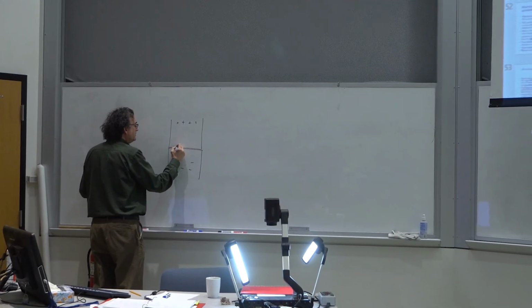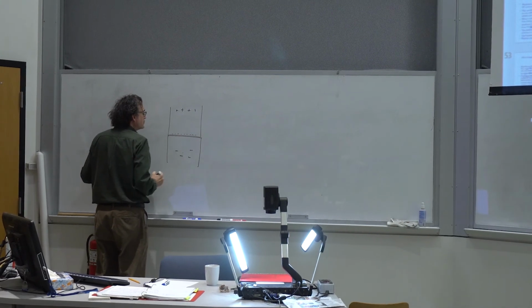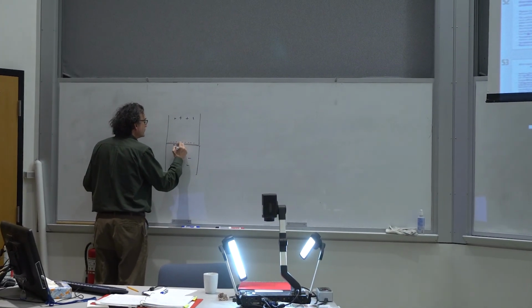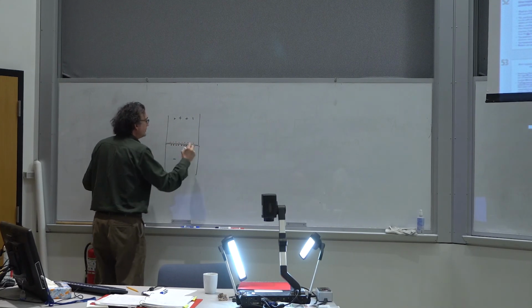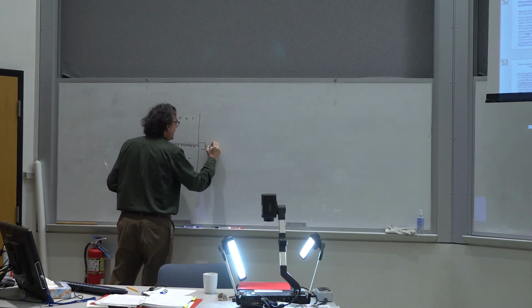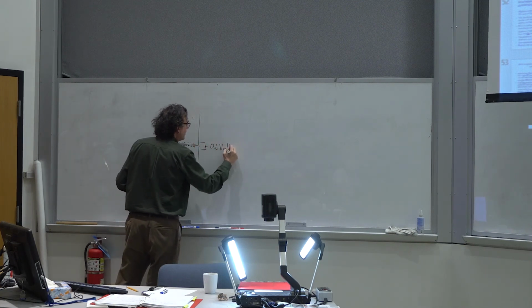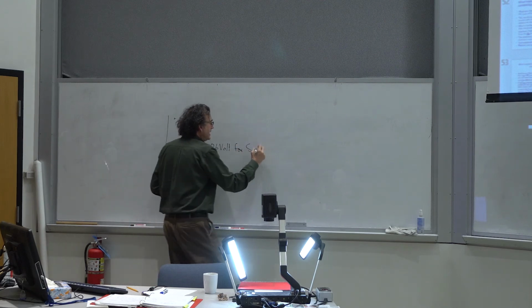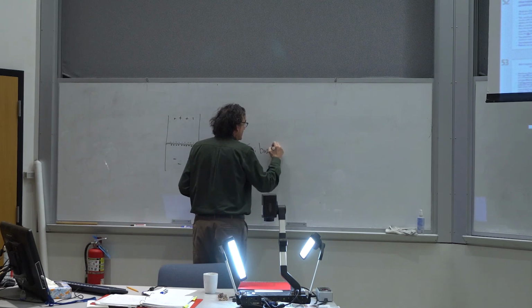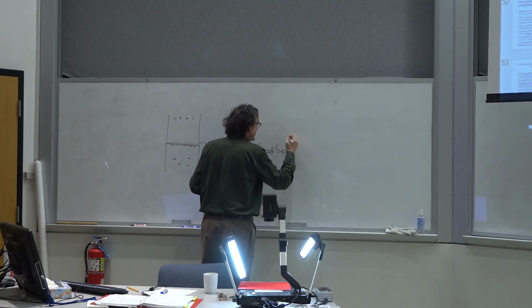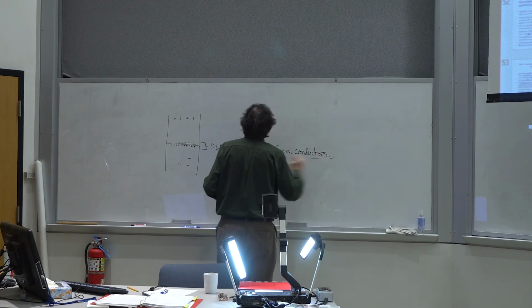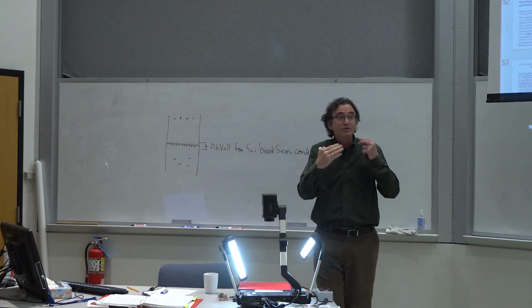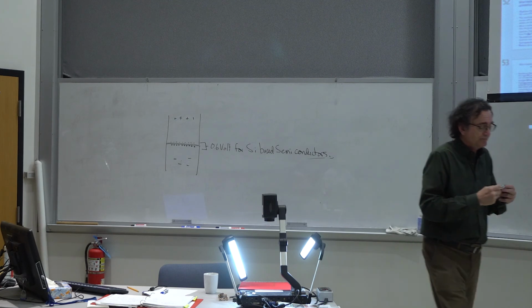So at the junction, I'm getting an excess of negative charges here, with the electrons that have jumped away leaving holes behind on this side. This creates on the junction a 0.6 volt potential for silicon-based semiconductors. For germanium, I think it's 0.3, but for silicon-based semiconductors, this is what you have. It automatically creates a voltage barrier.